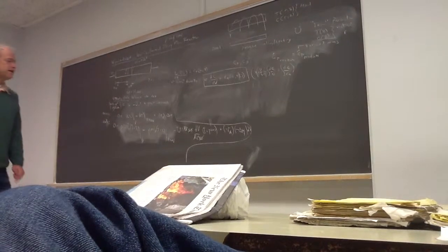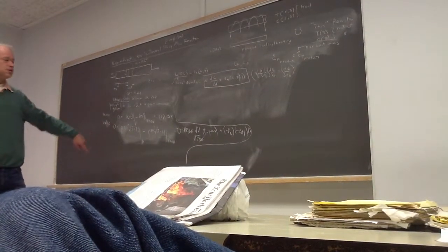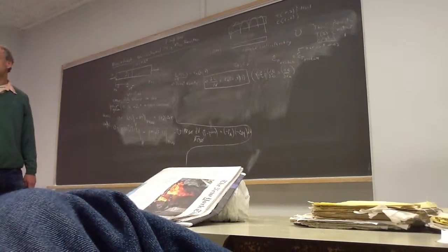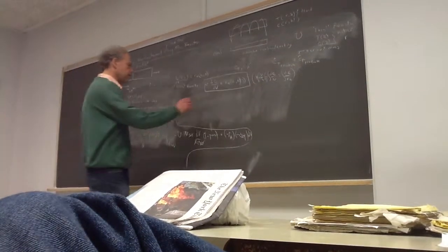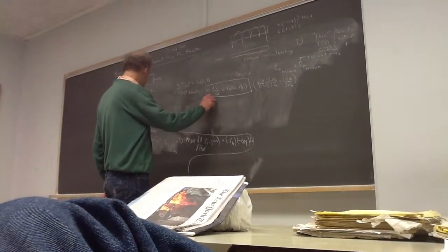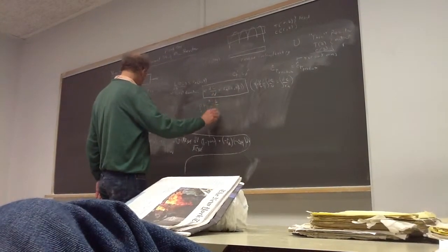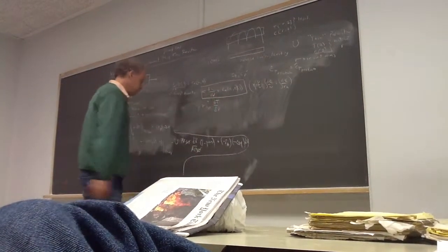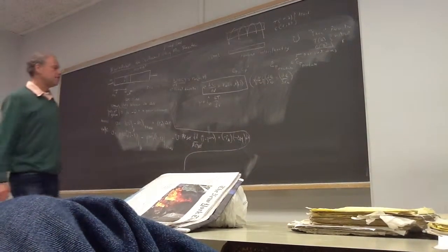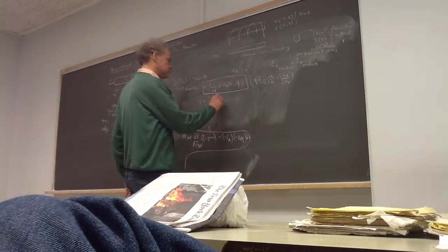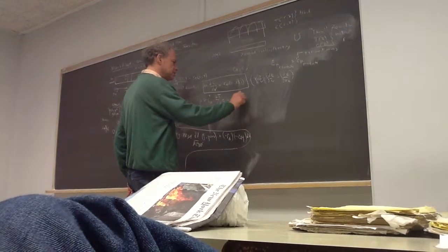Okay, so let's now bring these two terms to the other side of the equation, divide by dV, and take the limit as delta V goes to 0. And if I do that, again at constant density, I get rho Cp hat dT/dV, because the T0s cancel out. And that's equal to minus RA of C, T.